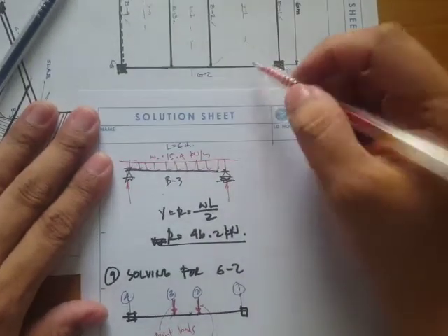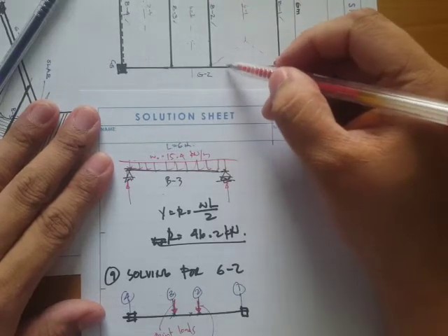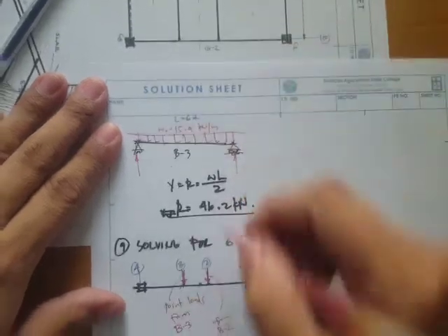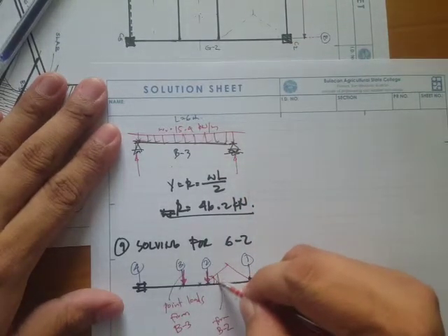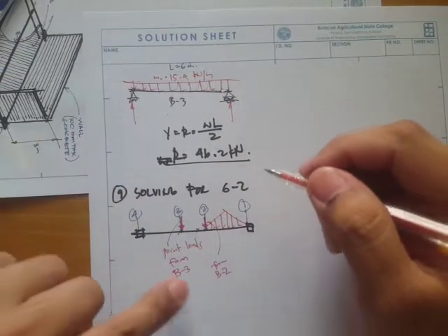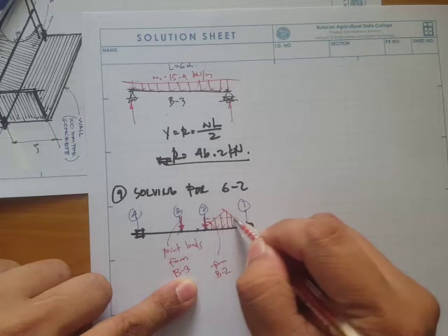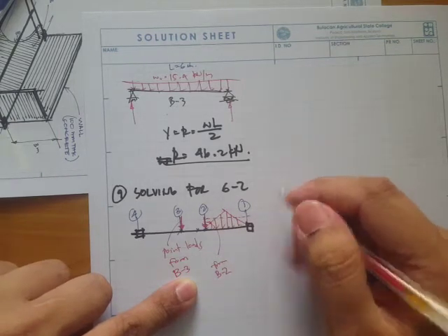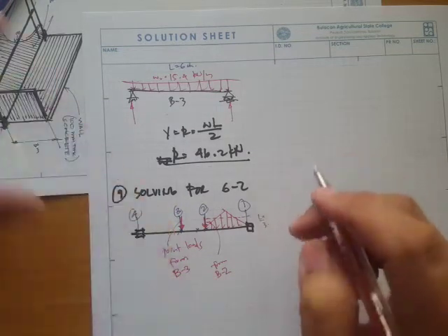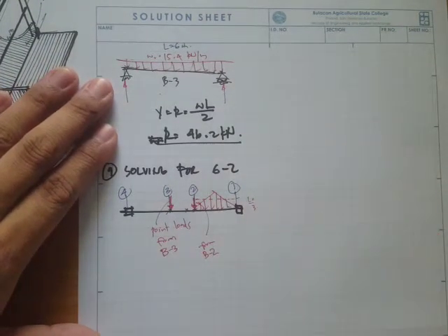But on this side, slab number 1, since this is a two-way slab, it's actually contributing loadings to the girder. So we have a triangular loading, something like this. But again, we try to simplify this and we use the reduced value of Lx over 3 as the tributary width. So that's going to be the setup.